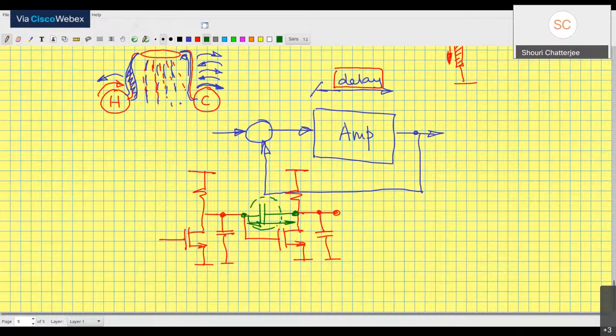How small should the small signal be for applying a small signal model? There is no "how small." If it's not small enough, then make it smaller. That's the answer to your question. If you want to talk mathematically, then your answer is that it should be infinitesimally small. However, infinitesimally small is not going to do anything for you. So you want to have some amplitude at the input, but if you think that amplitude is large, then make your amplitude smaller.